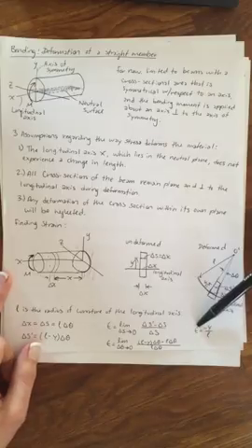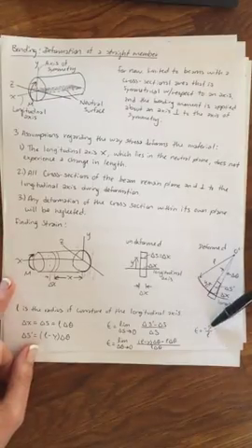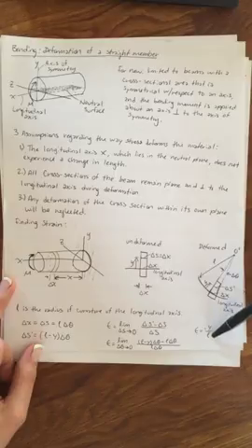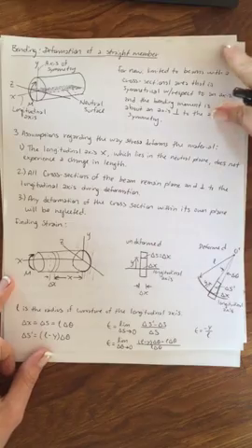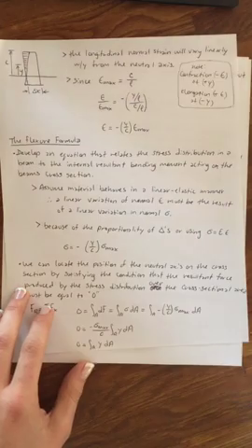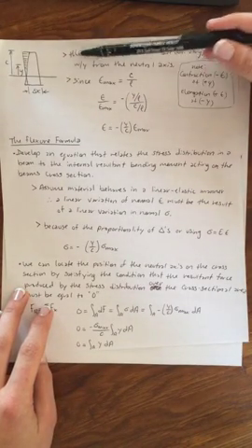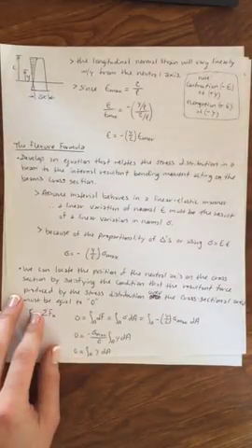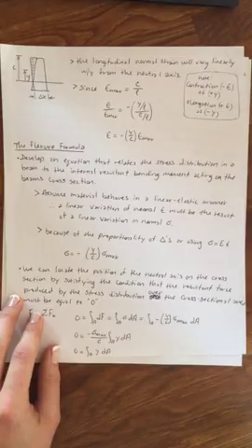Therefore, using this proportionality will be really handy for us. We can say that the strain is equal to negative y, this distance to the segment, over rho, this radius of curvature of the longitudinal axis. Okay, so that tells us something that's really important, just theoretically, that the longitudinal normal strain varies linearly with y from the neutral axis. So linear relationships are always great.